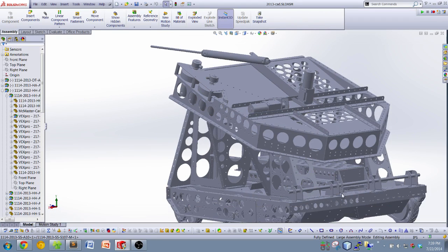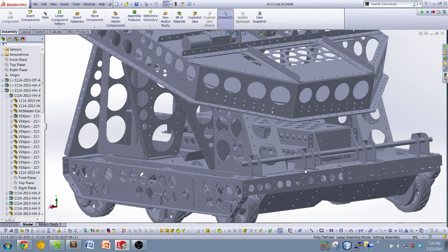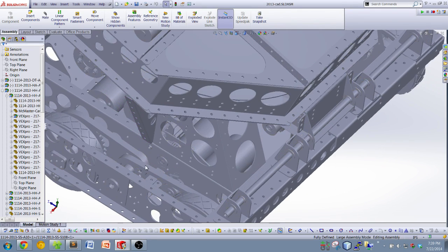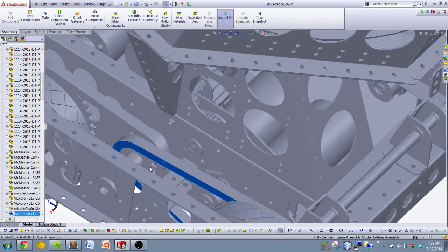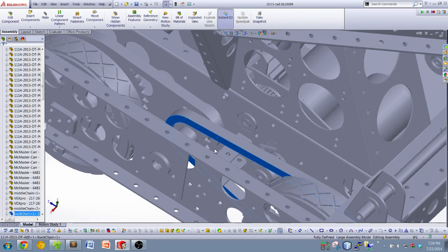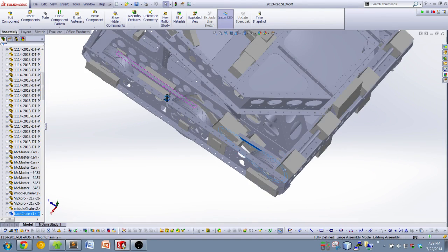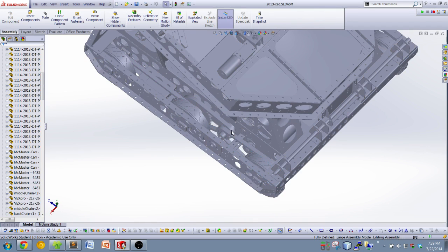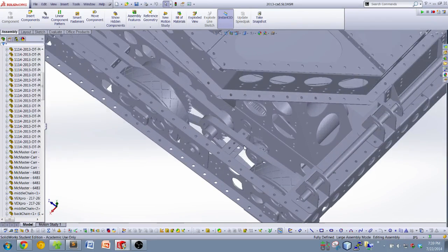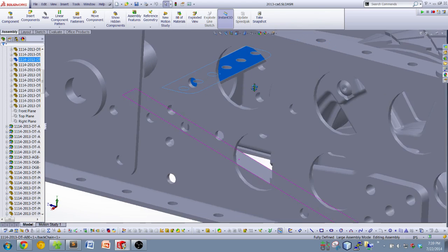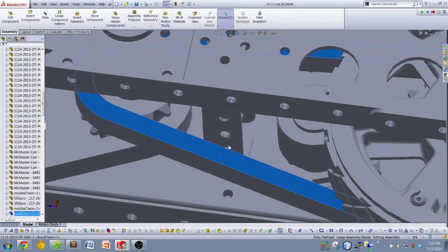Do they do anything that's not sheet metal? I think they're almost entirely sheet metal too. But you can see they go even as far as CADing their belts, or that's a model of chain because they're running sprockets here. You could make real chain, but it's not worth it. So there's an efficiency, right? There's no real reason to make it look good if you know that it's taking up the right space. So they do this to make sure the chain path doesn't hit anything. They have this bar in here for support, and they want to make sure the chain path's never going to hit that. So they CAD the actual chain path.